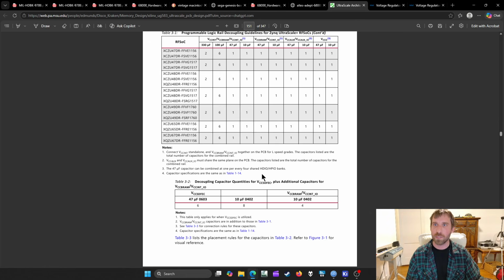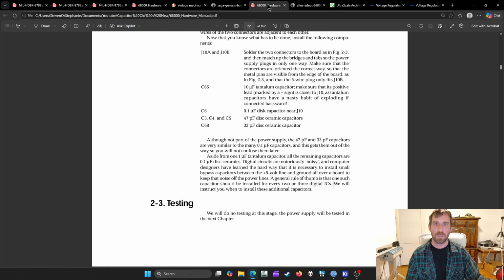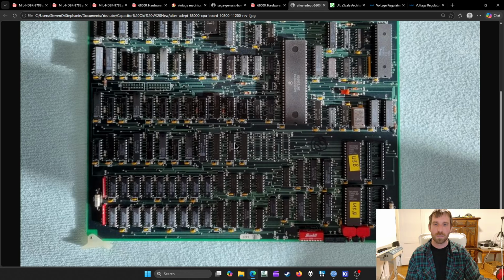So for what we're doing, just do what the data sheet does. And just remember, you could, if you wanted to, in many cases, for most designs out there, you could just not have a bypass cap and you would be okay. You don't need to obsess with this. You don't need to get into the tunnel vision on it and have it take away your valuable time and brain power. So for most of what you're doing, just put the darn thing on and then move on.